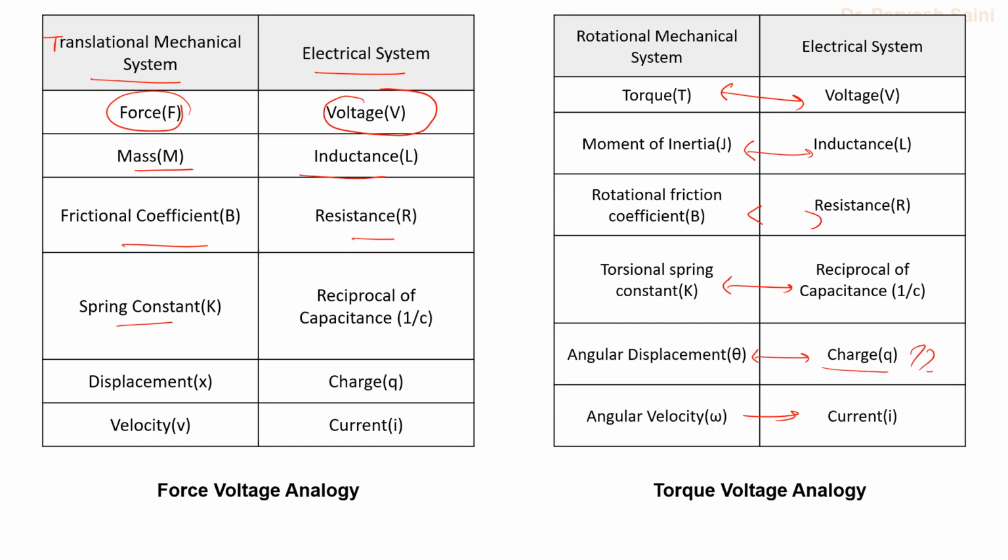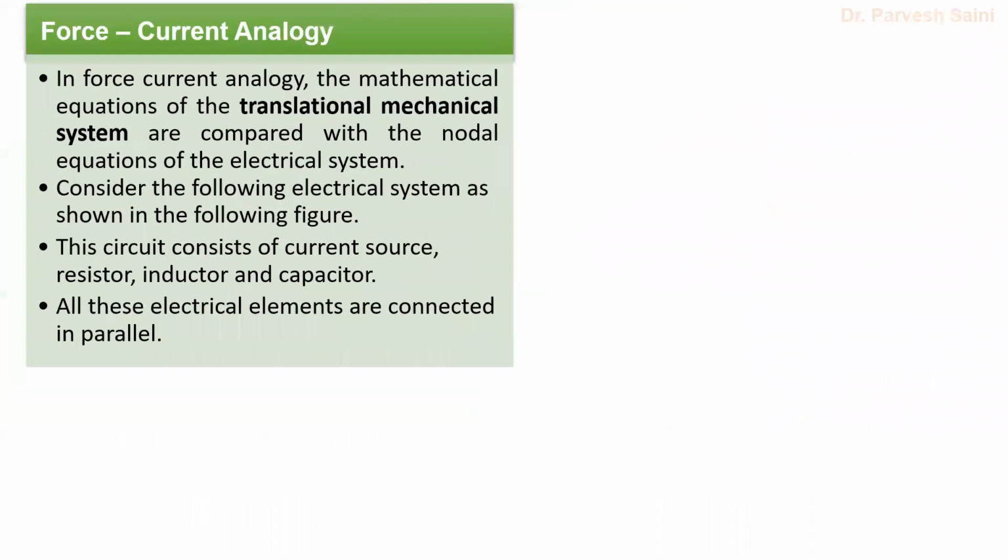So similarly, we can have the force-current analogy and torque-current analogy. Now, what is the force-current analogy? The force-current analogy is basically the analogy in which the mathematical equation of the translational mechanical system is compared with the nodal equations of the electrical systems.